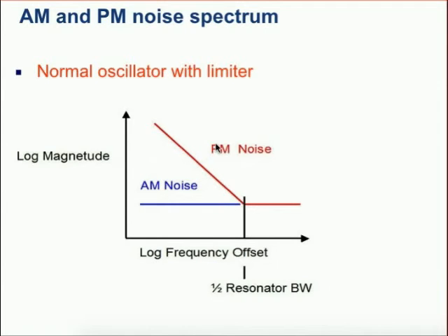Well, this is what flicker noise is doing with the resonant system in the oscillator. Flicker noise is a noise modulation of the phase shift in the amplifying device, and this is something that's closely linked with the whole resonant system, because the positive feedback is connected with the resonant system and can pull the frequency.